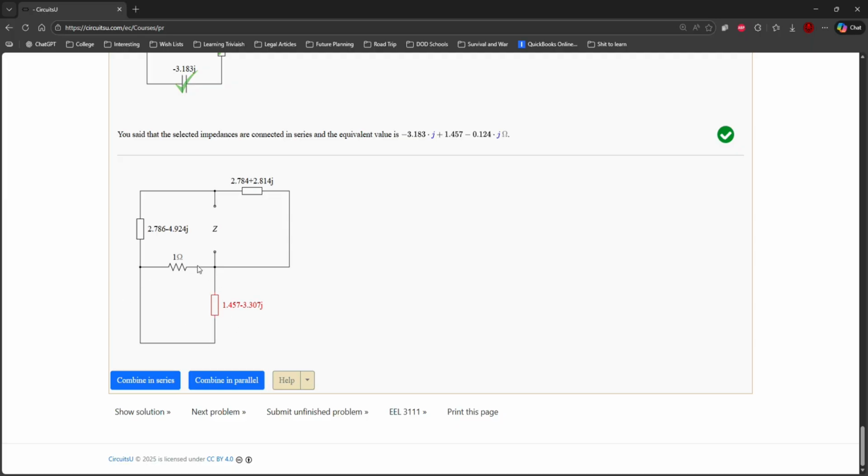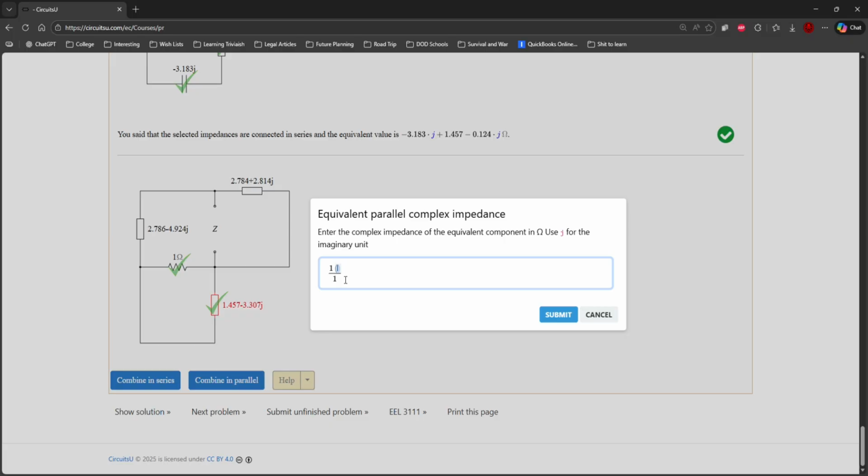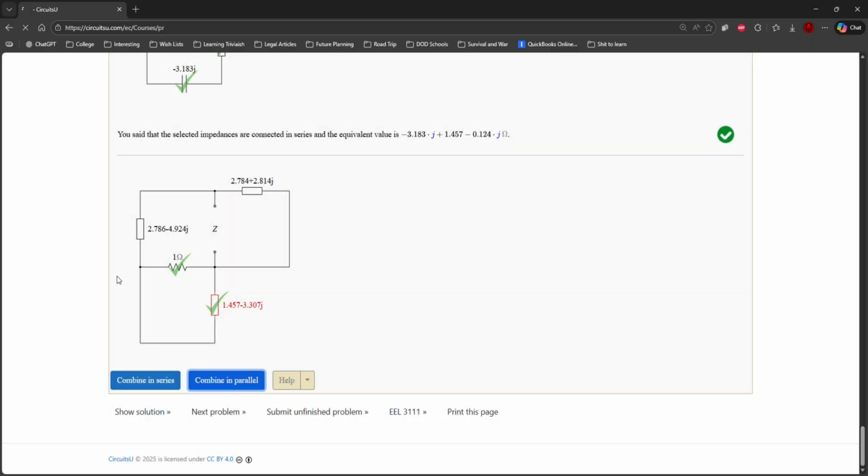Okay, now we'll do another parallel combination, which will allow us to have our 2.78 and our current 1 ohm resistor in a series format, all in the same left side loop. And then at the very end, we'll have the 2.7 and the other 2.7 be in parallel. Thus, we are a mere 2 steps away from finishing this circuit. If you got the gist, you're welcome to stop the video now, but I'll proceed here to completion.